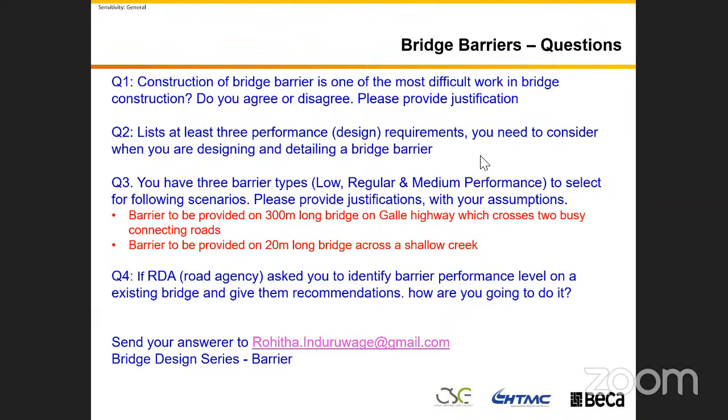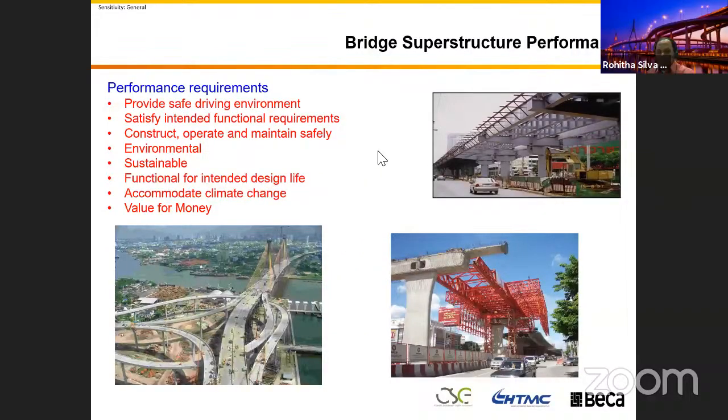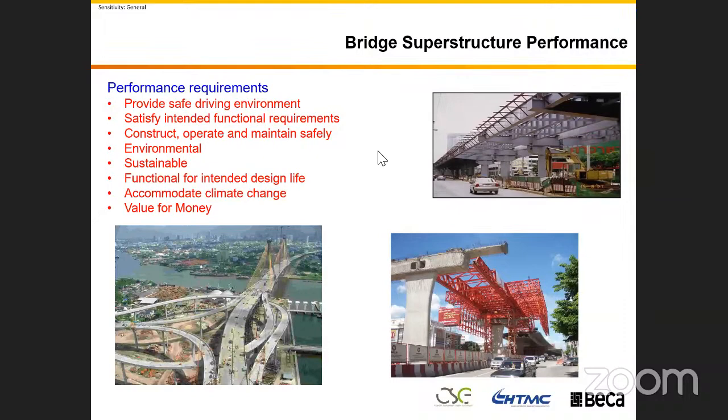Any questions? Mr. Rohit? Yes, this is Arthur from CSCC. I have a question with regards to the heat of hydration in piers specifically, because sometimes we need to construct this pier in one go. We need to cast the concrete in one go for the pier, and this can develop temperature differentials in the core and the bottom, because the pile cap is also restrained and it's cast early.